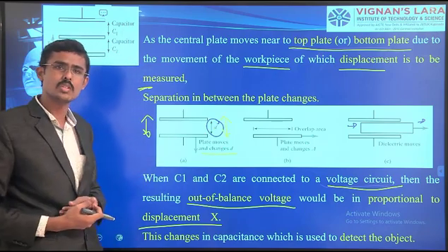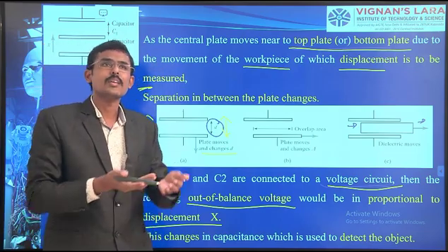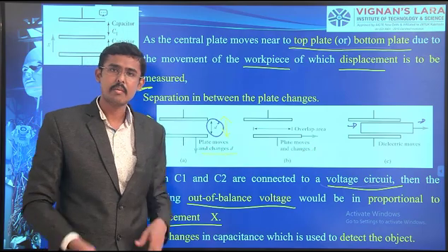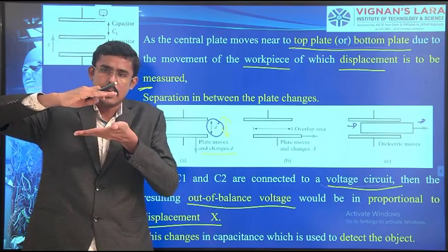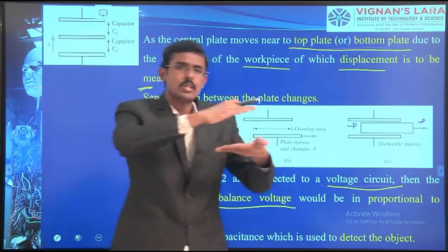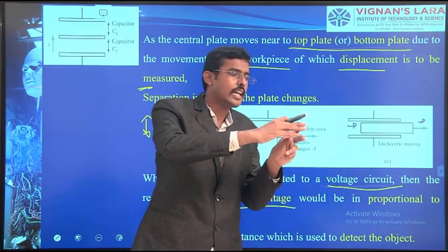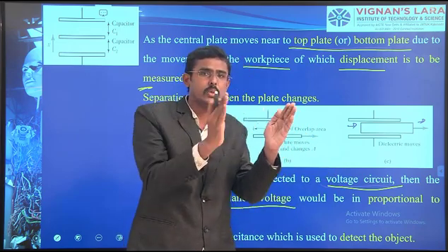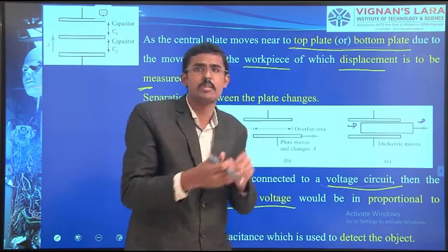Where can we use this? Let us consider an example of measuring an increasing water level. The dielectric medium can be the air, the vacant air. We have two conductive materials with air in between, and we have calibrated this. Now I am keeping this setup near the water tank. Here the electric field is generated. We have seen the electric field due to the attracting and repulsive force. The electric field is generated in between.